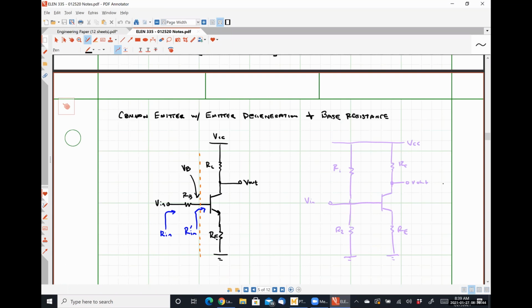Yeah, so the honest answer here really is that we can use either of them if we can make our input network look like a single resistance, which we totally can. Or we could simply use the common emitter with emitter degeneration as our second stage, and then figure out what the gain stage is in the first.